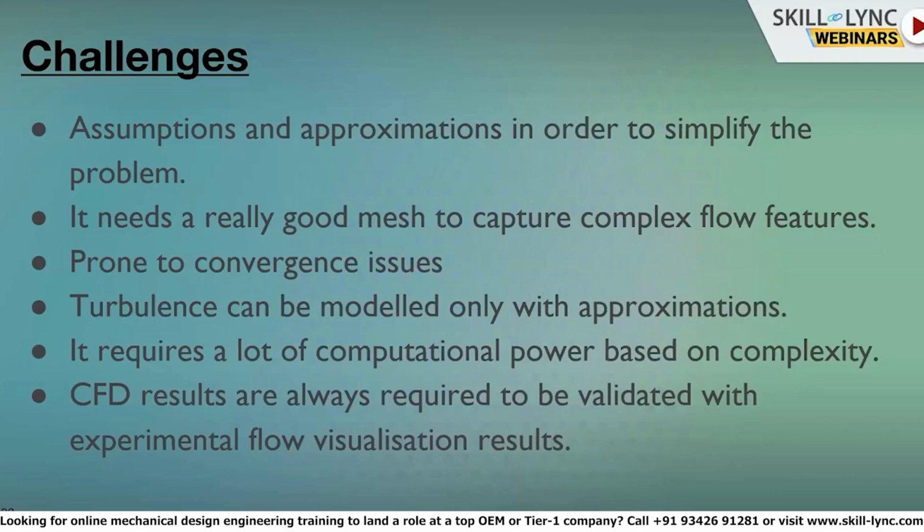certain aspects of the challenges. Then turbulence, as I said, can always be modeled only with approximations. So it is not always going to be 100% that we capture the turbulence. That is also a challenge. Then computational power, as we already discussed. And the most important is that CFD results always need to be validated with experimental flow visualization results, and you need to quantify the error you are having with your experiments. That is an important thing.